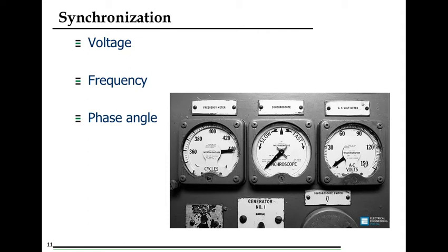It doesn't matter whether the generator voltage is greater than that of grid or grid voltage is greater than that of generator. But while synchronizing, we keep our generator voltage higher than that of grid so that we are the source of reactive power at that time. Okay, so if the grid is at 400 kV potential, then we keep our generator and GT terminal voltage at suppose 402 kV or 401 kV.